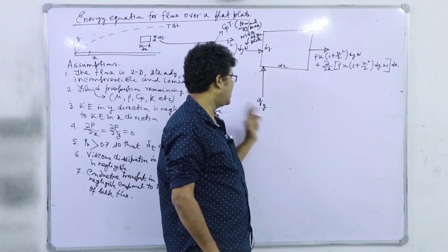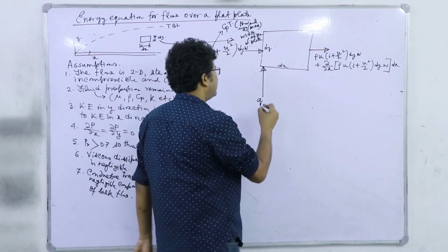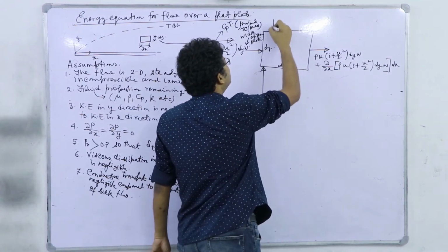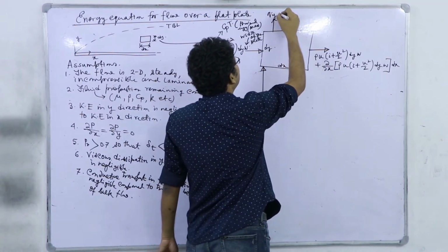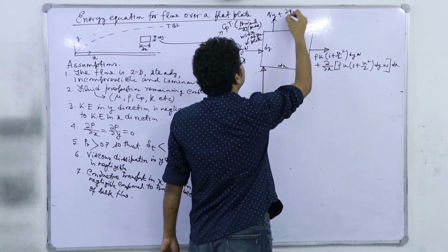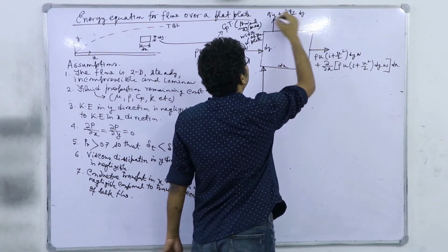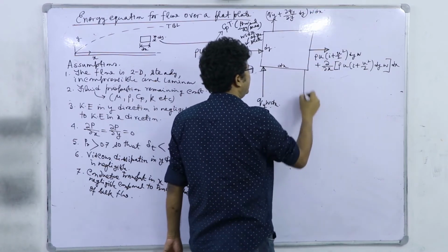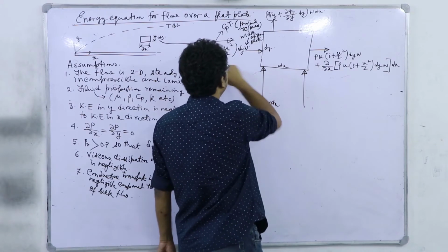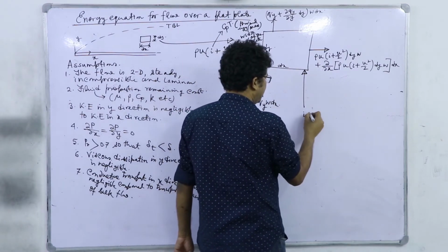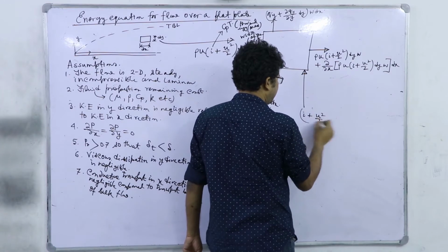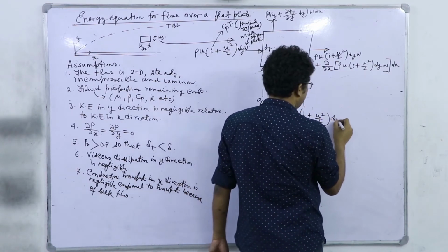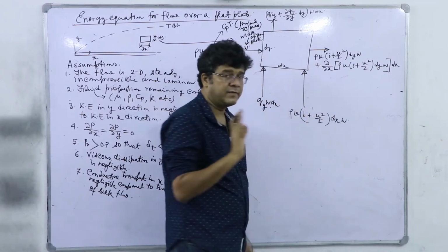So this is the conductive heat flux, multiplied by w into dx. So here we will have Qy plus del Qy by del y into dy, whole bracket, w into dx. Additionally, we will have the same sort of thermal plus kinetic energy, u square by 2, rho into v into dx into w, and that's the beauty of energy transport.